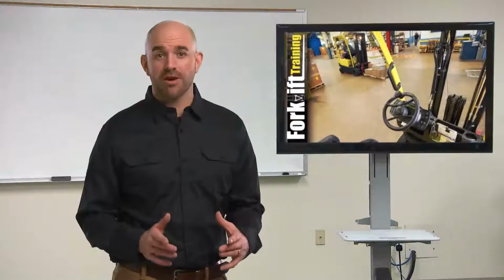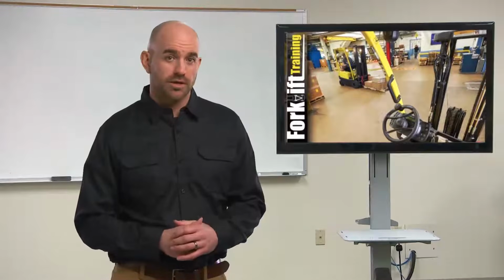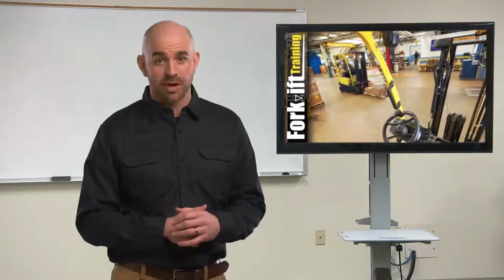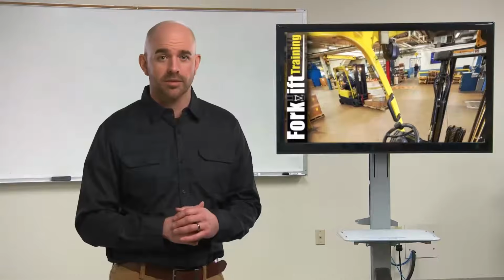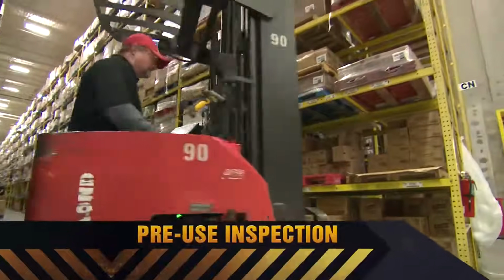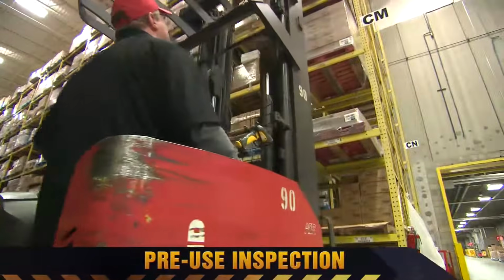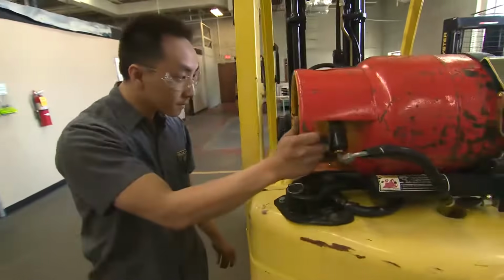Always practice safe operating procedures every time you step up to the controls of a forklift. Remember, you're the one person responsible for your safety and the safety of others when operating this equipment. The very first step in safe operating procedures is to make sure your forklift is ready for the day's work ahead. OSHA requires that all powered industrial trucks, including forklifts, be examined at least daily before being placed in service.